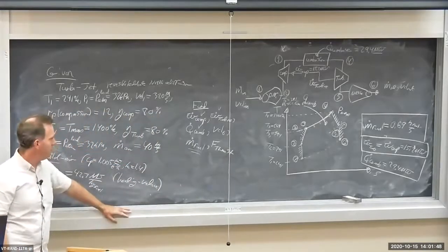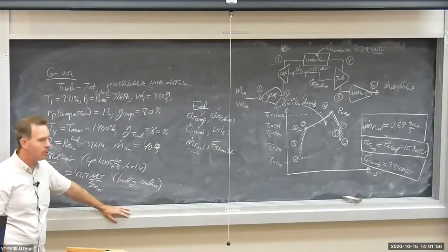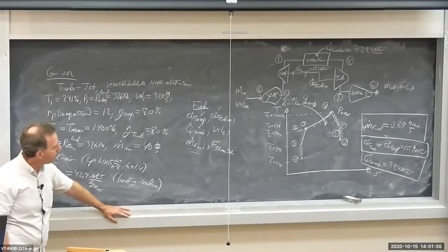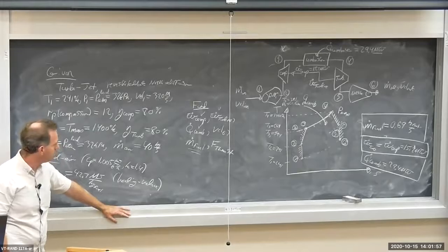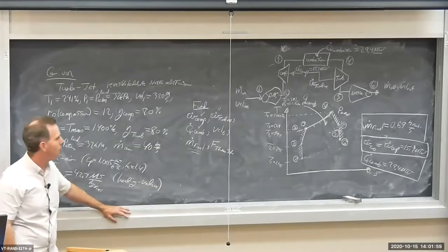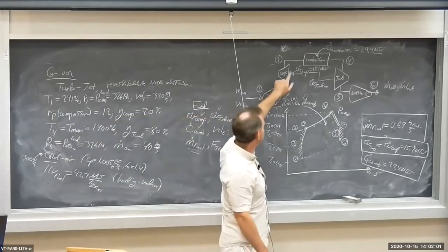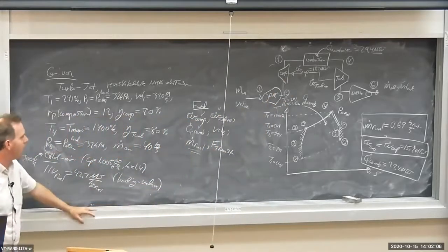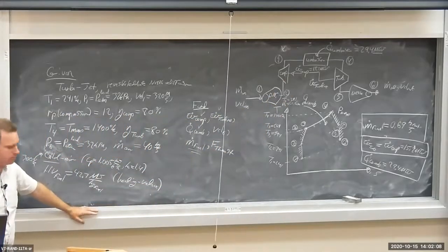We're at a difference of about 1.5% variation. So the M dot going through the turbine and the nozzle is about 1.5% higher than going through the diffuser, the combustor, and the compressor. Who cares? That's why we're assuming M dot is the same all the way through.